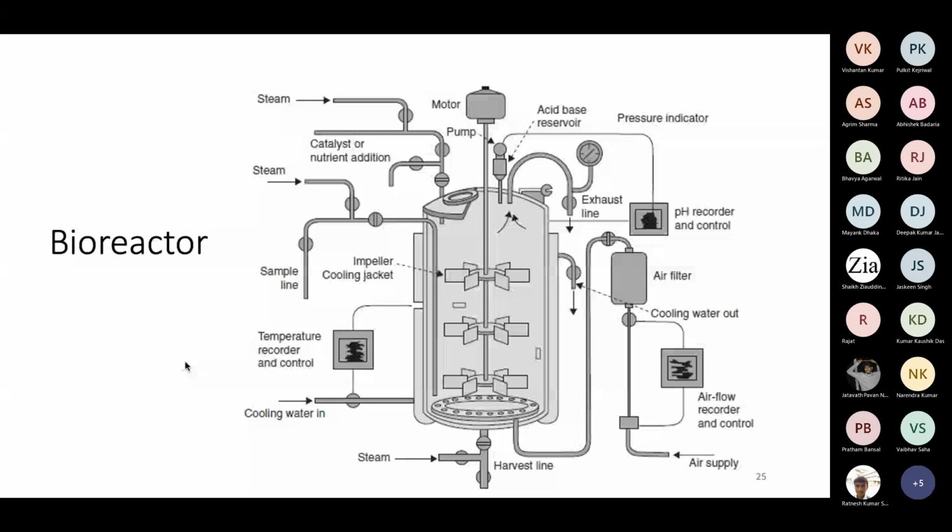So after having the liquid level on the 80% volume, if you feel that the upper section, means above the liquid level, the headspace area, the shaft rod is actually not making any help because you don't need any mixing or impeller in that headspace region.